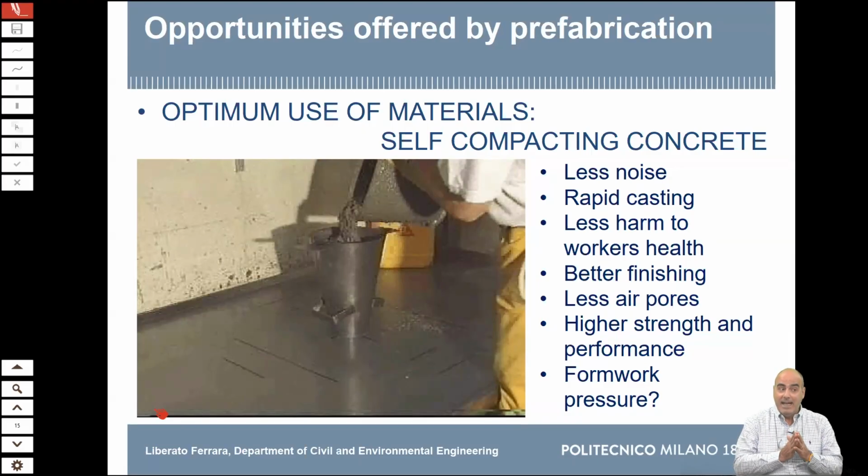performance of the material. There is one question mark: the pressure on the formwork. As we said before, formworks have to be designed. There are models, we will see them tomorrow, but self-compacting concrete is a fluid, and as a fluid you should design the formworks for hydrostatic pressure. This means that probably some formworks should be over-designed with respect to other kinds of application, but there have been technology developments to help with that. But an important thing that we must not forget is always that we have to take care of the formwork, also because even in cast-in-place construction, formworks can be an important cost item.